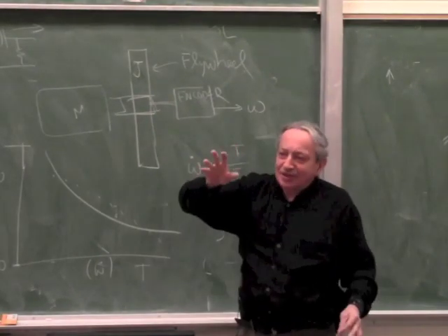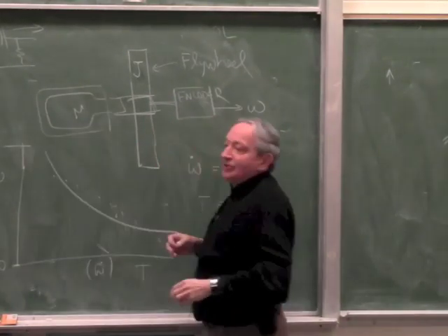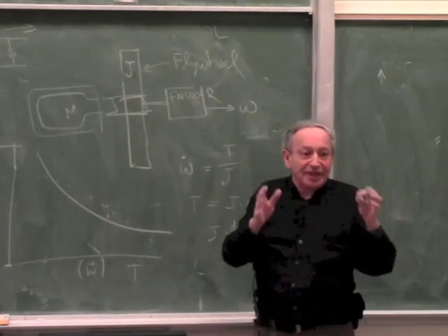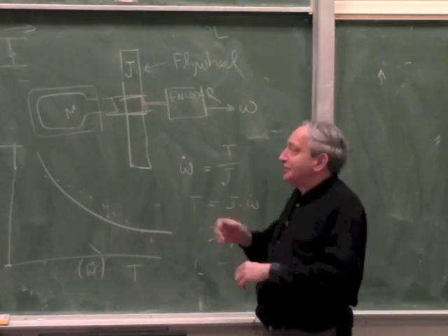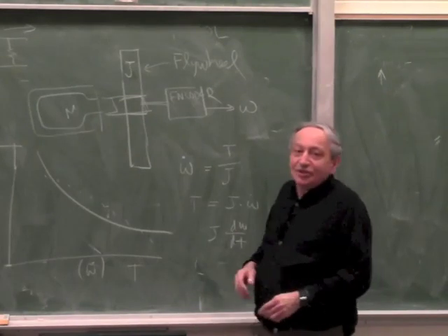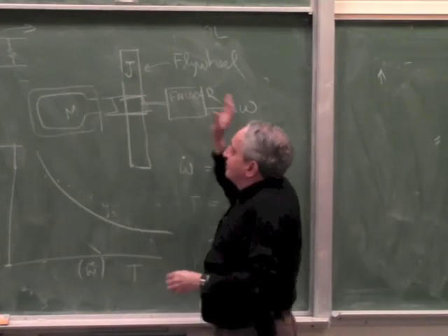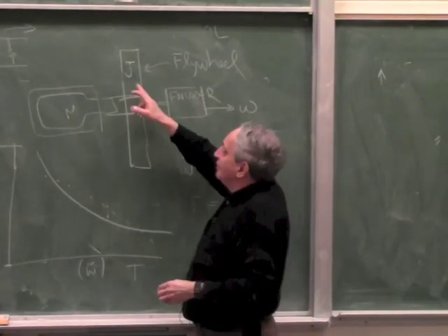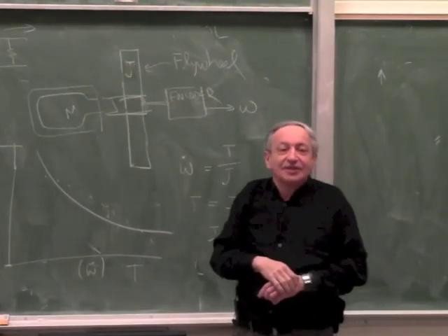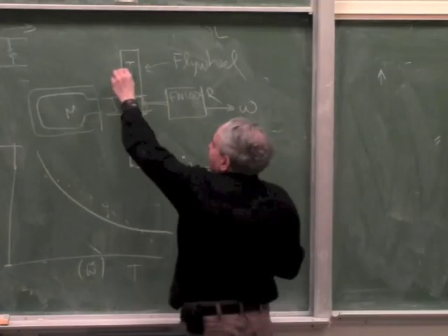Now some people say, just a minute, you don't know J because the motor has some internal inertia that you don't know. Okay? Which is true. You just know the weight that you added, but you don't know the internal inertia. So how do you get around that without complex measurements? Yeah, exactly. All you do is you either add another J or do it without the J. You do two plots, one plot without the ring and one plot with the ring, because now you have one more unknown and one more equation, right?